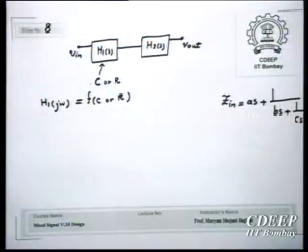But one of the reasons it is used a lot in filter implementation is simplicity in the implementation and regularity. Because you can design and optimize a specific biquad as a filter library element, and then simply scale the values and make a cascade. So if you want to have, for example, migration to another technology, this is a very straightforward way of doing that by using cascade.